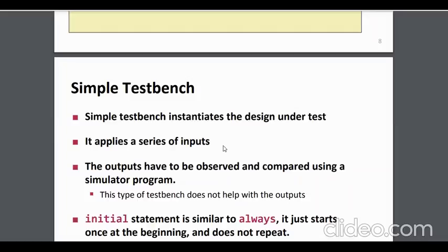The second main thing is, inside your design module the inputs are declared as wire, whereas the outputs are declared as reg. It is quite common, right? Input as wire and output as reg. But in the test bench, it is vice versa. Why?